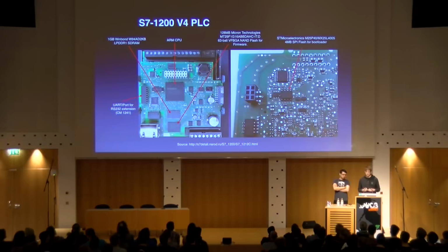Then a second stage of the hardware initialization happens, and at this moment it waits for a specific command for half a second, and if it receives this command, it goes to another mode, which we'll discuss later. Otherwise, it prepares a CRC checksum table for the firmware, and then it tries to load the firmware, and then eventually it removes the memory barrier, the SY instruction, for those who know ARM, and maps the firmware to the memory.